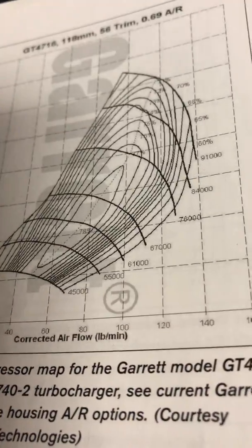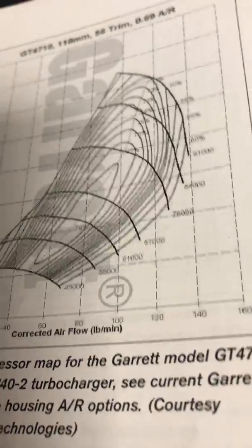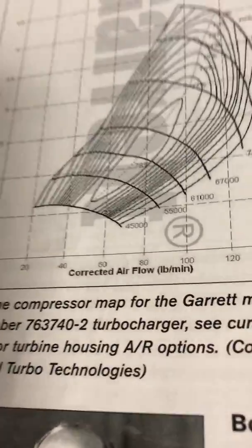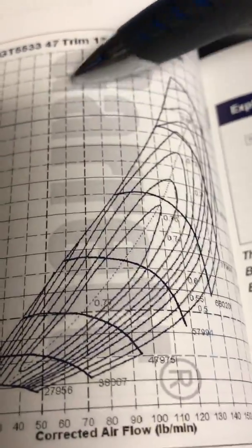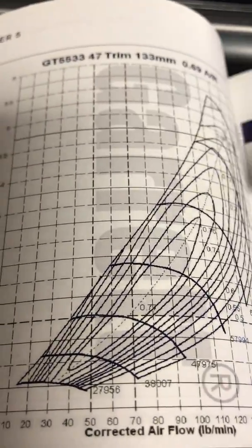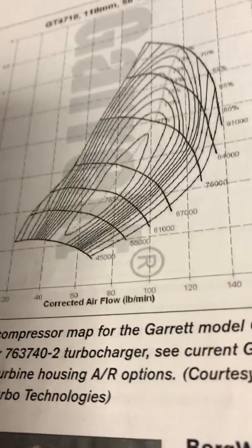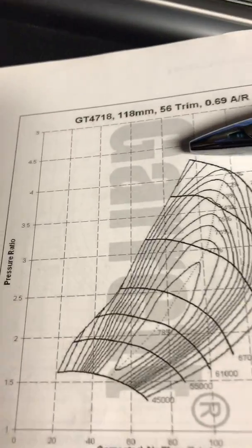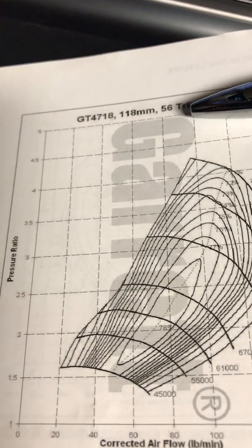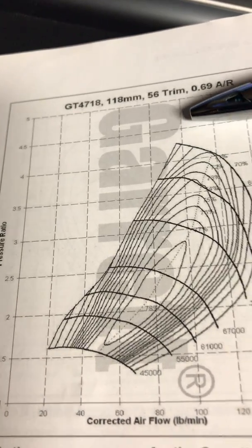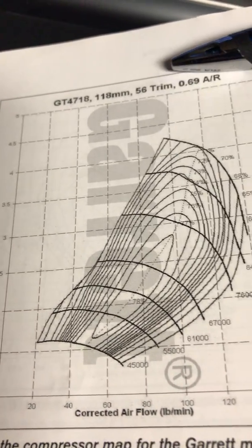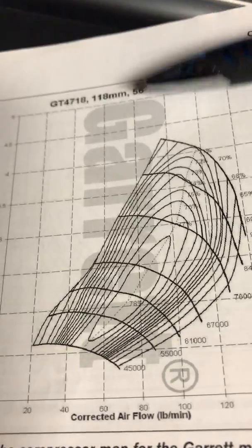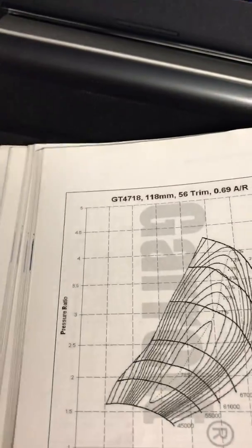Now granted, they've been upgraded. There's Series 2. There's a lot of upgrades to these turbos, but they're not going to make that much difference. If you're out here, the latest and greatest is not going to put you on the map. GT47, back to the mid-80s. Up you go, upwards to 5-to-1. More than likely this line is going to continue this way, so 6-to-1 is going to put you overspeed and in surge. That's not going to work either.